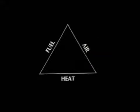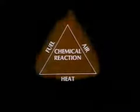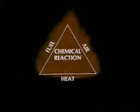The third requirement is heat. Heat is required to raise the temperature of the fuel-air mixture to a point where a chemical reaction or ignition takes place. The chemical reaction is the fourth requirement. If any one of the requirements is missing, combustion will not occur. The two requirements for steam production are water and heat. The heat is provided by combustion. Boilers are designed to allow the requirements for steam production and combustion to come together.